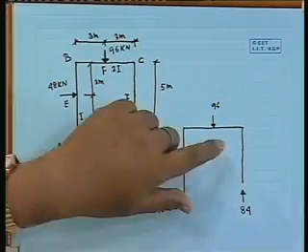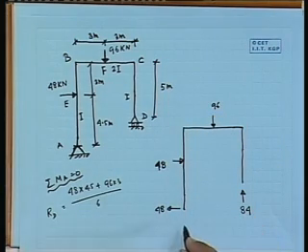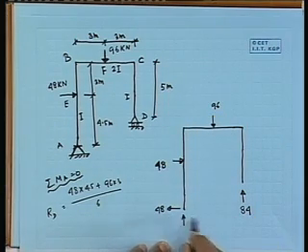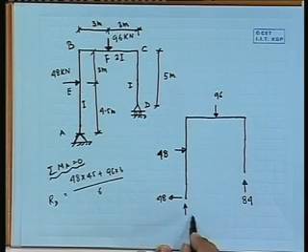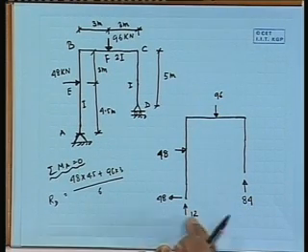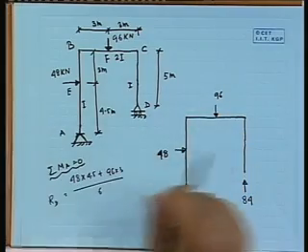Now, the next option is if it is 84, that the vertical force is 96, this is 48. So, there should be another force here. So, it will be 12 kilonewton, 12 plus 84 equal to 96, summation of all upward forces. Now, if you have the reaction 48, 12, 84, we can proceed for finding out the moment at the different segments for capital M.